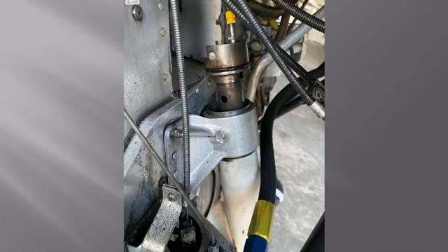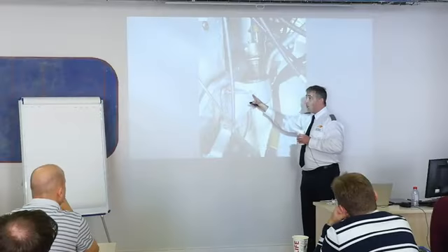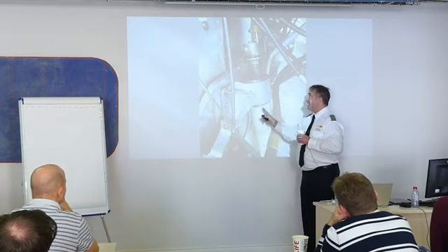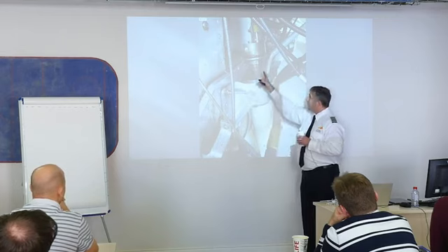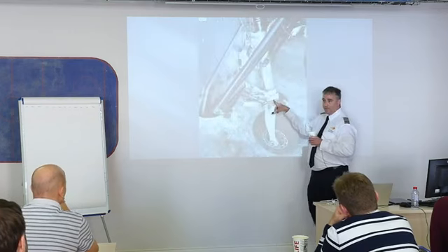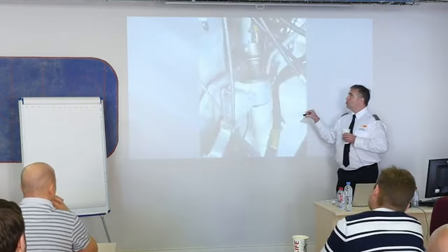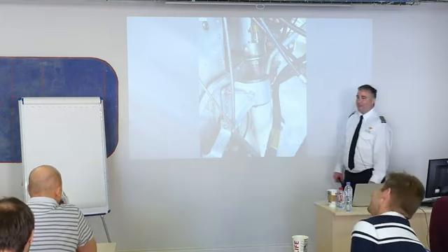Whoa! This is the cylinder. The strut goes into there. That's a bolt that should go through this hole. Okay? Somebody landed this airplane very hard and broke the bolt in the entire strut. And you can see, like you said, there's nothing here. No strut here at all. Okay? Don't do that. I got plenty of examples of what not to do.